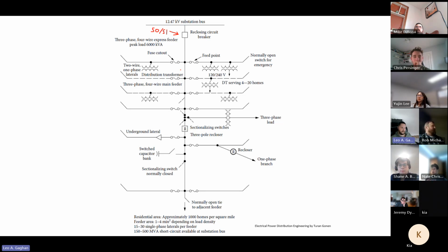And then these fuses, the more current you have, the faster they blow. So these are all for coordination. The goal is if a fault happens right here, current's going to flow through here. We want that fuse to be faster than the overcurrents on our breaker, so that just the fuse can pop.